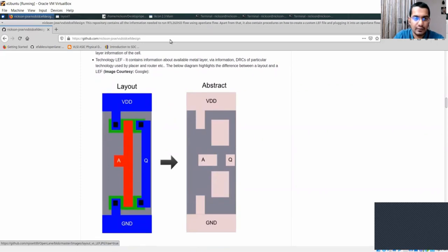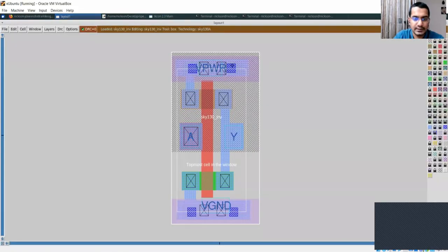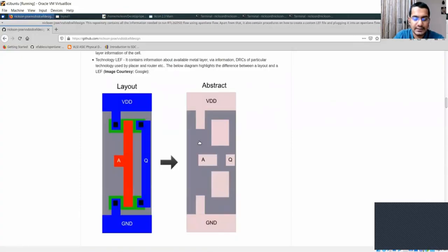We will use another mask, which is mask 14, to drill the contact holes. The steps remain pretty much the same. You use mask 14 to drill the contact holes in a similar way that you did for here, and for here. So now when you use this, you again do the same thing. You deposit a thin TiN layer, and the reason for depositing TiN remains the same.